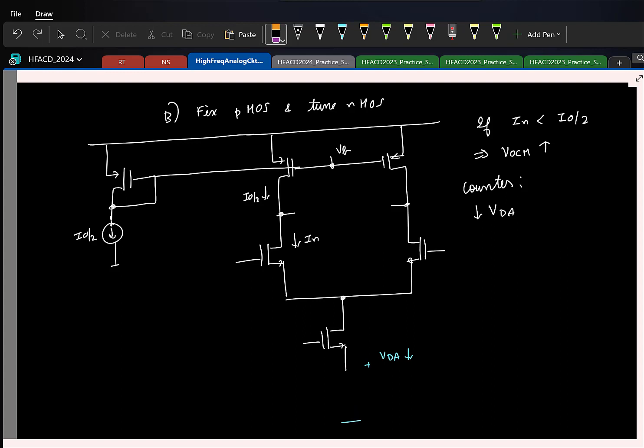So I can basically replace it by this and feed the common mode. Now again, to generate the common mode, you can do this VOP VOM, but if you do this, once again you will have resistive loading. So if you want to avoid that, you can take a cue from what we did in the last thing. Yeah, so here you again see that we are getting the common mode in terms of voltage, but the final action is happening in terms of current.